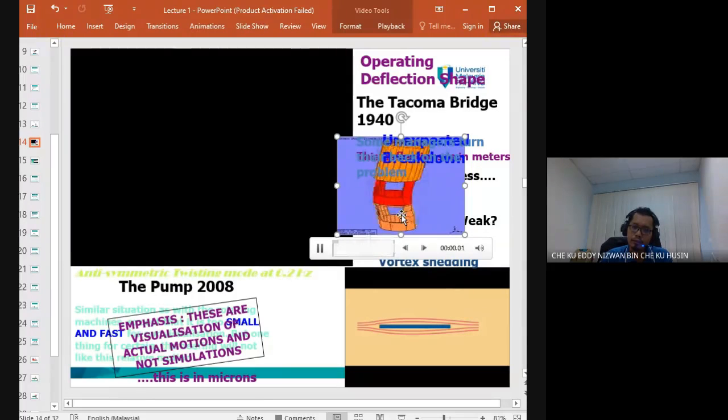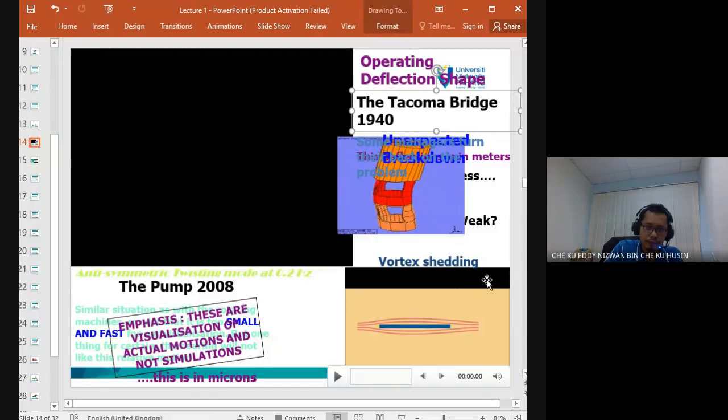So to reduce the vibration you have to modify the structure. For this case, the solution is to increase the stiffness in the middle part, with a few webs on this component, to add stiffness and increase its natural frequency in this bending mode. After that the vibration can be reduced. This is just an example of the application of vibration.